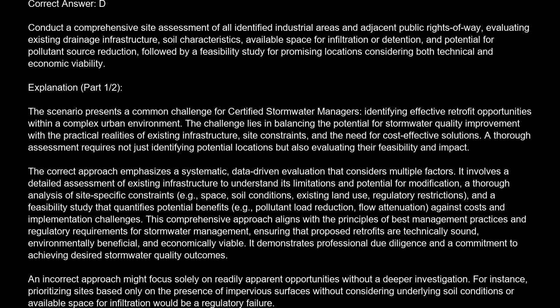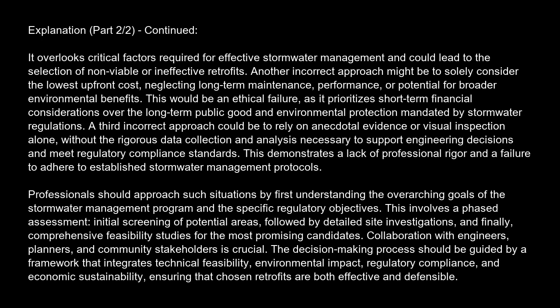An incorrect approach might focus solely on readily apparent opportunities without a deeper investigation. For instance, prioritizing sites based only on the presence of impervious surfaces without considering underlying soil conditions or available space for infiltration would be a regulatory failure. It overlooks critical factors required for effective stormwater management and could lead to the selection of non-viable or ineffective retrofits.